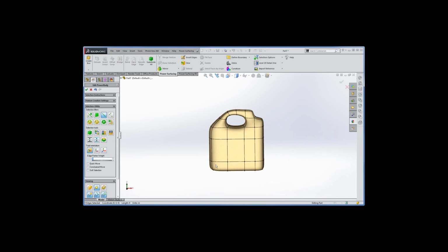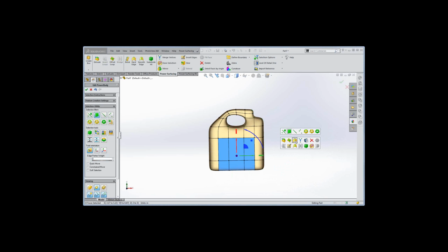And then I want one more matching loop over here before I do the center inset. So holding my A key down again, click, and I'm ready to go. So on face mode, I'm going to select these interfaces, and I'm going to give them a hard edge. And you'll see it change at the corners a little bit, not too much. Right-click to accept, and I'm going to do an offset.